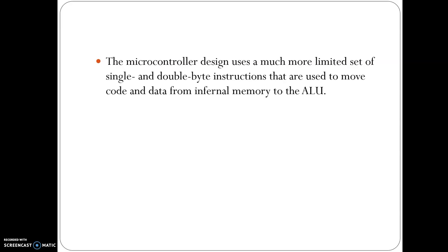As I said, whenever I have to fetch or read any instruction for the microprocessor, I have to first place the address on the address bus. That address from the program counter will be placed on the address bus and given to the external memory.